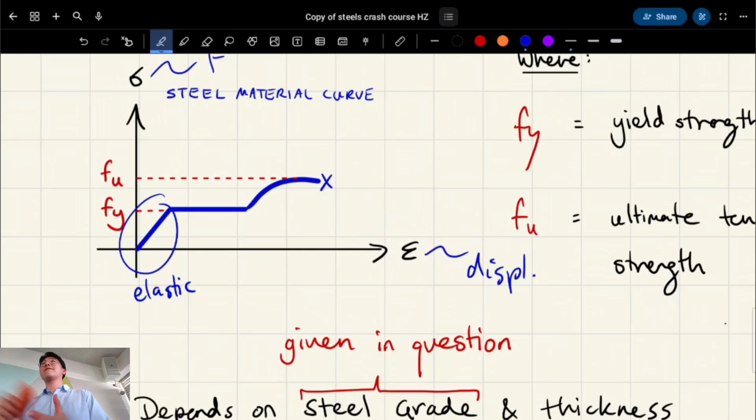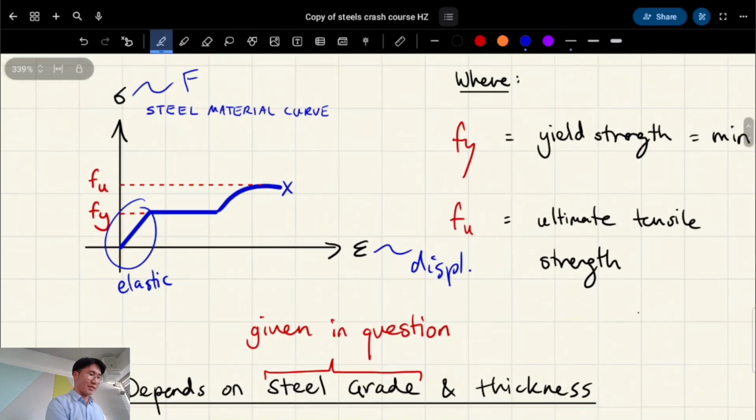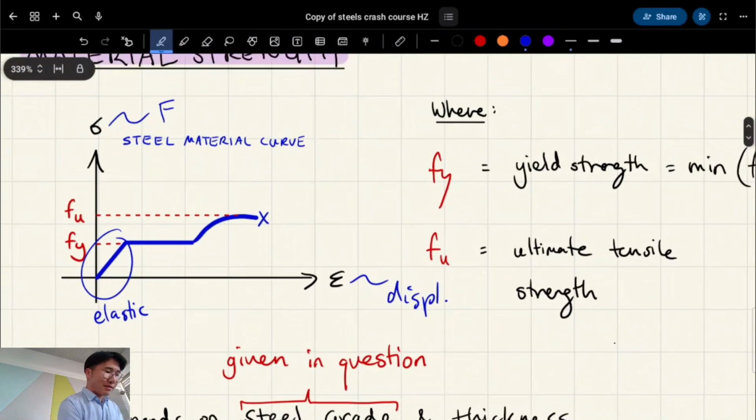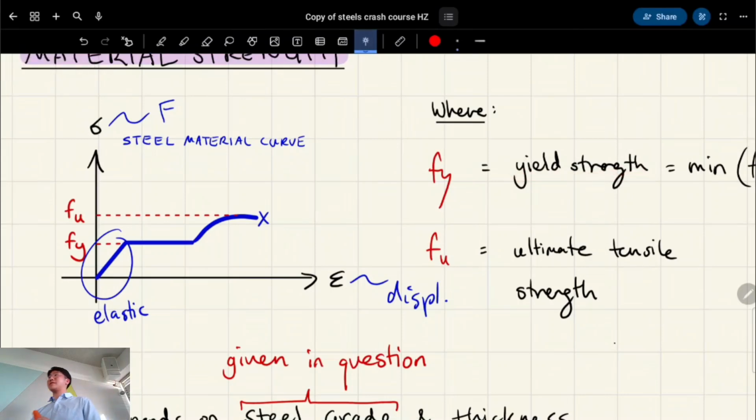What's happened in the steel? Because it goes into the plastic region. When you stretch more and more of it, it gets more plastic the more you go. Yes, there's a word I'm looking for. Strain. Necking. Yeah, it's the result of it. But what's the steel doing? Yes, perfect. It's yielding. So that's the word we're using here. On the right, this is the yield strength of steel.